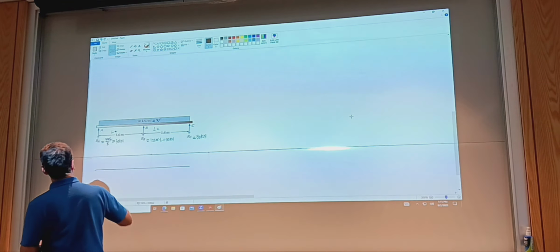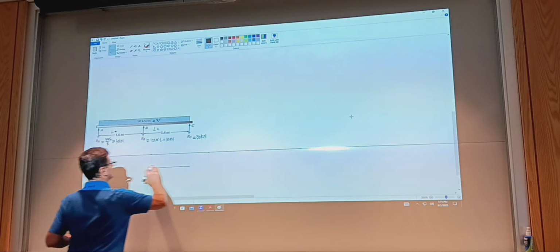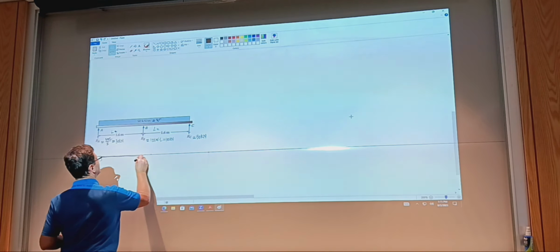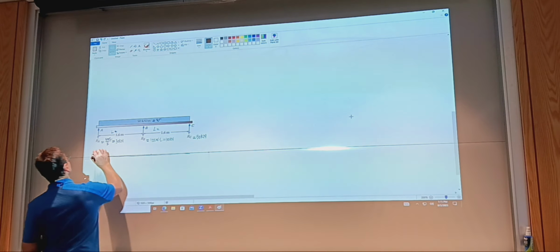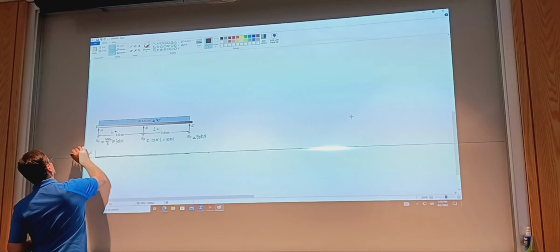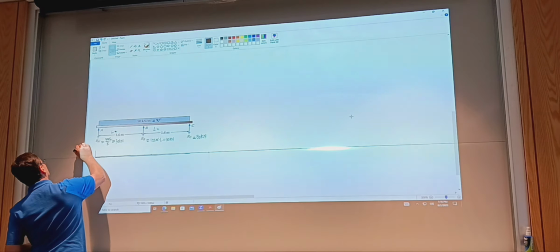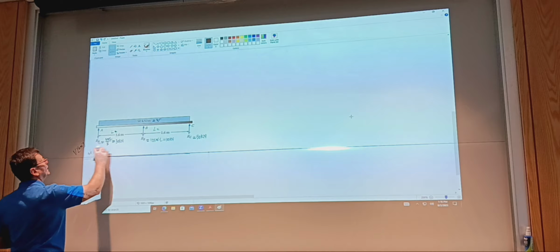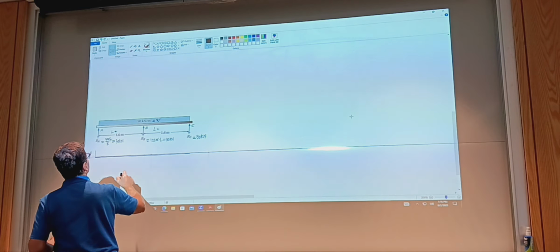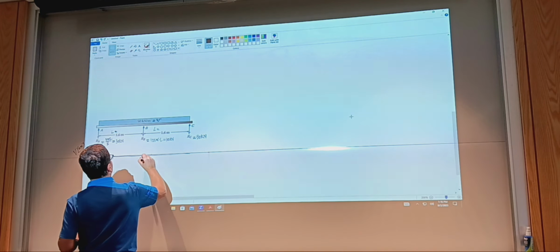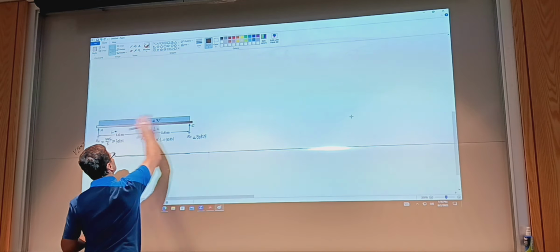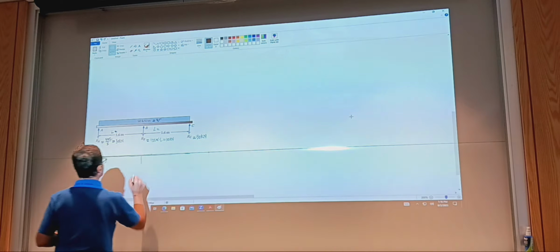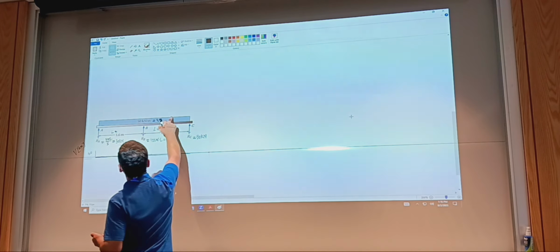So we begin, I could move a little bit up. Actually, I could stay on this line here. So 30, in the V axis, in kilonewtons. So jump by 30 up, and then I have an even distributed load, and so that will cause V to decrease at a slope of 50 kilonewtons per meter.